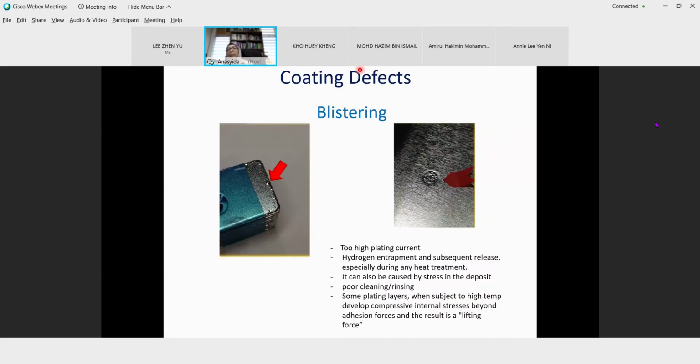Okay, all right, so we have completed the coating processes. We have learned about electroplating, and electroless plating. For electroplating, we have two: electroplating and electroforming. We also learned about electroless. We were also introduced to hot dipping, and the most common in industry is galvanizing.